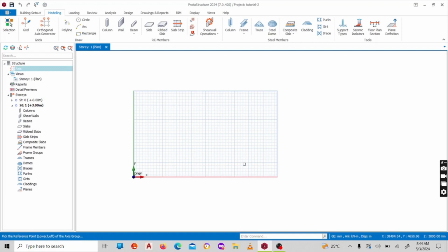Back again. Today we're going to learn how to work with grids, and I'll show you how to place columns and how to place walls and how to make slant columns and slant walls, as well as how to design columns that come from the highest floor level to the basement of the ground, a continuous column that does not break within floors.